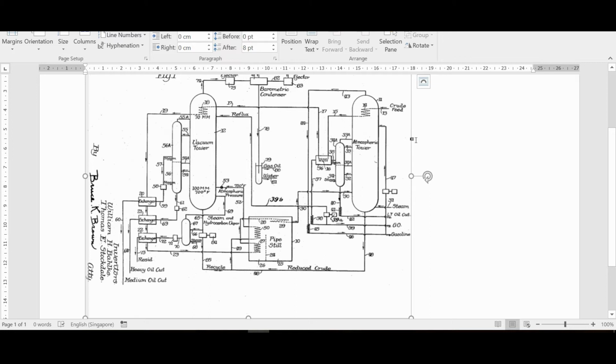Well, basically, you've seen some preheating being done before. So what this does is to conserve the heat that's being used in the tower. This is known as heat integration, so you can reduce the boiler duty. The idea behind distillation is that you must have a condenser on top. So you need a cool fluid to cool the vapors that run overhead, which is a mixture of steam and naphtha. To cool that down, you need to take heat away from that.